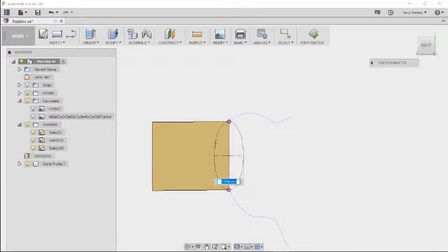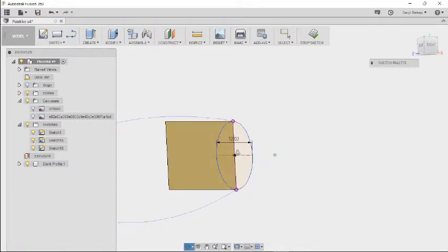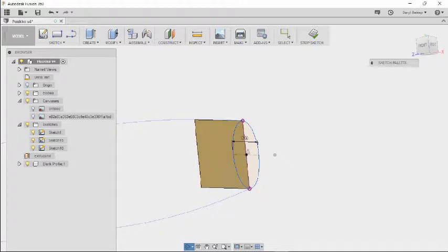Click that. Now I'm going to come down here to the side and create a 12 millimeter wide on the shorter dimension of the ellipse. I just created 12 because it's close to 4 times the width of the blade blank, and I thought that it would look like a good proportion. Enter. Now we have an ellipse at the end of our circle. Alright.